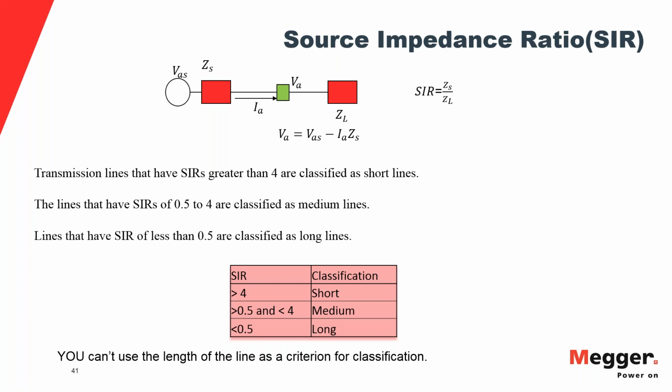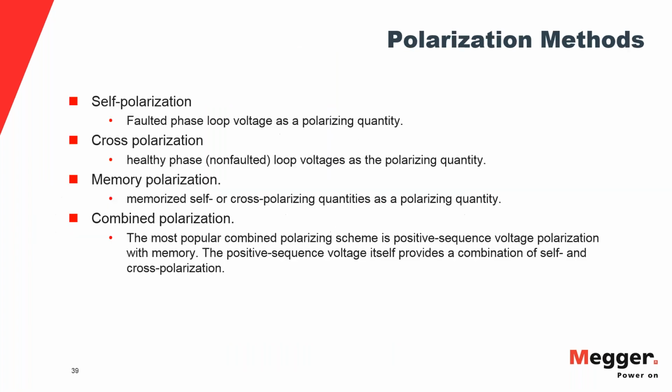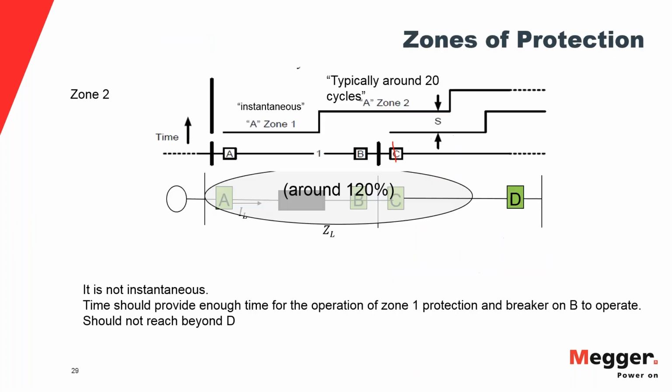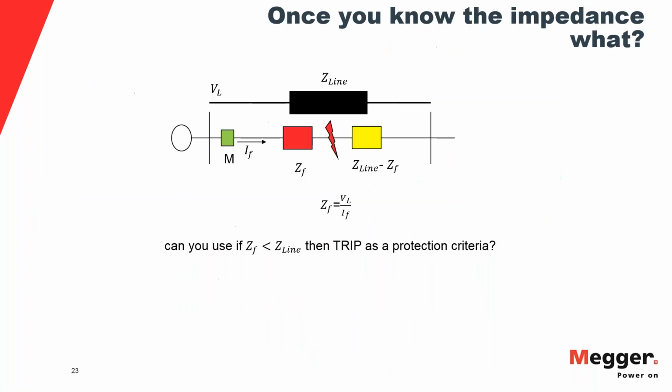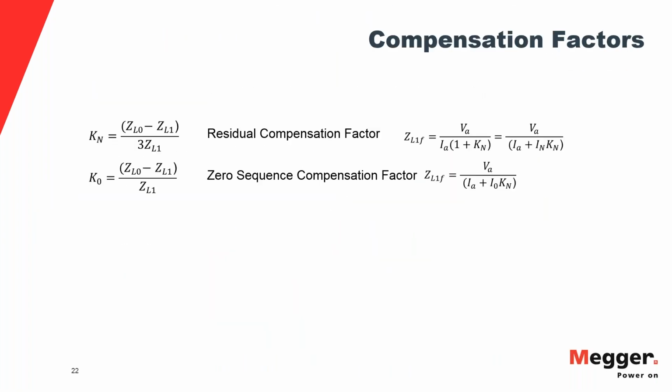Okay, compensation factors. In this case, I'm going to assume that the person is talking about the KN factors that we presented here. Yes, the compensation factors. On the settings of the relays, you will tell the relays the relevant impedances, and the relay will compensate, okay?